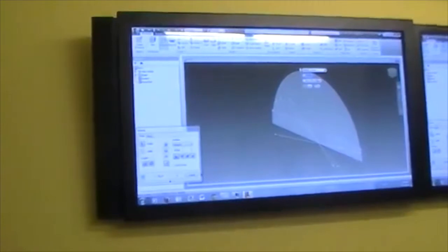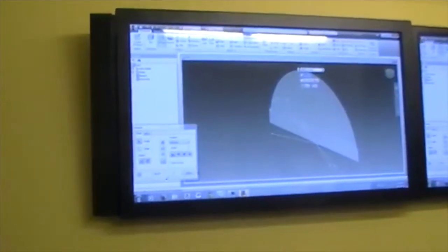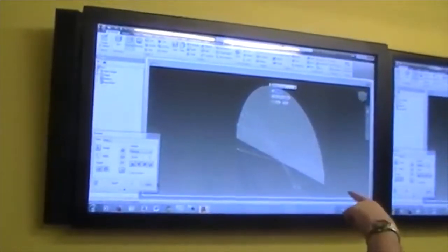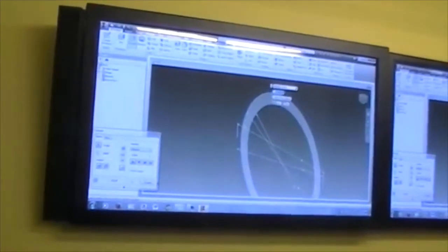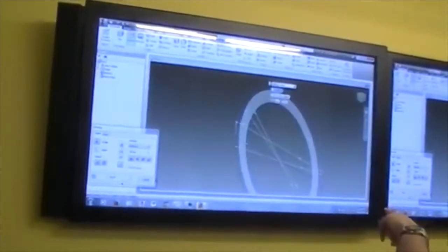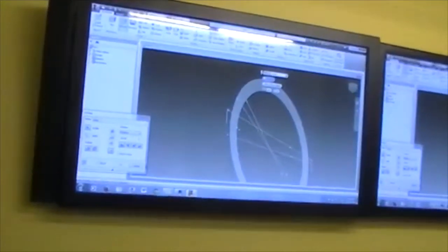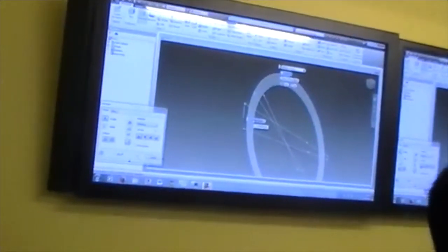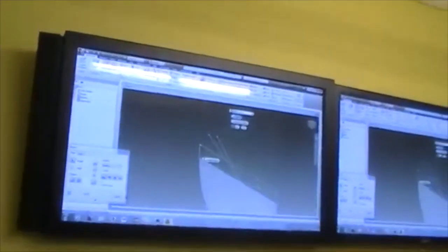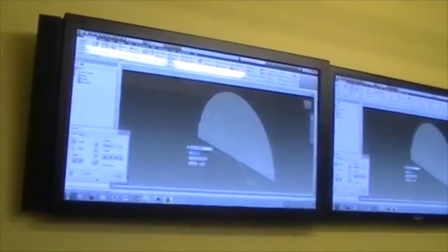Actually, I'll show you guys cutting as well. I'll do that with the same view. So we'll use the outer view. I was going to go back in and reconstrain the points because sometimes, if I'm just trying to select that inner circle right there and just the top part of it and it's not selecting, what that tells me is I need to go back into my sketch and constrain points for this point right here and this point right here. But instead, you know, I'll just leave that for now.